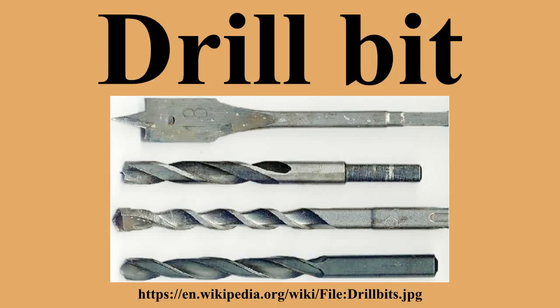Many different materials are used for or on drill bits depending on the required application. Many hard materials, such as carbides, are much more brittle than steel, and are far more subject to breaking, particularly if the drill is not held at a very constant angle to the workpiece, e.g., when handheld.